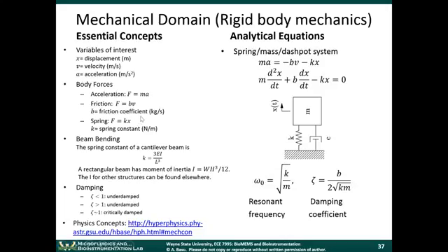So if we look at all these three forces together, we have this simple system here. The frictional force is represented by something called the dashpot. That's what this C is. Just to clarify, this C and this B are the same thing. So in this mechanical system, we have three forces at work. One force is acceleration dependent, force equals ma. Another force is velocity dependent, and then another force is displacement dependent.